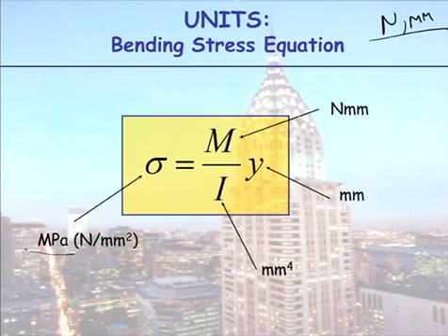So if you work in megapascal, which is a newton per millimetre squared, y has the order of millimetres, which is handy because our beams are normally a certain depth in terms of millimetres. So my member here is about 150 mil deep, so y would be 75. If I had to convert it to metres, that's 0.075 metres. You may make a mistake getting the decimal place in the wrong spot. So millimetres are the thing to use.